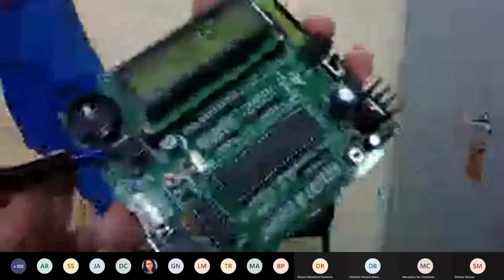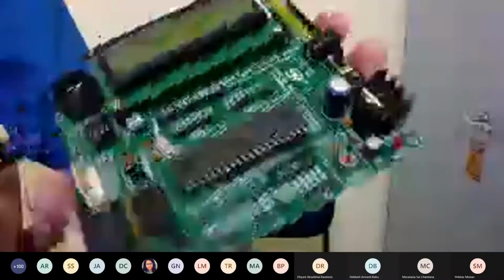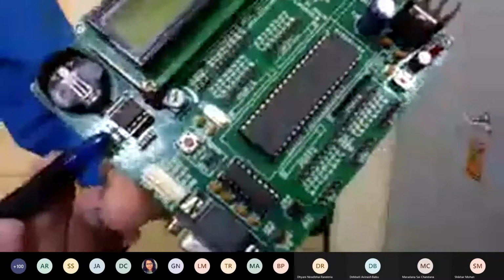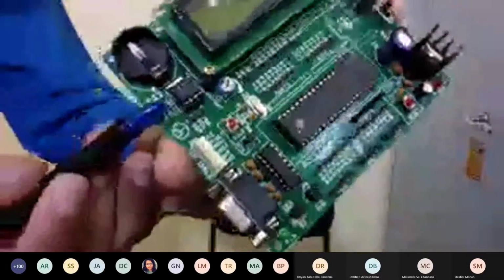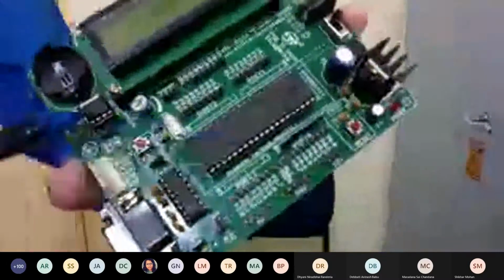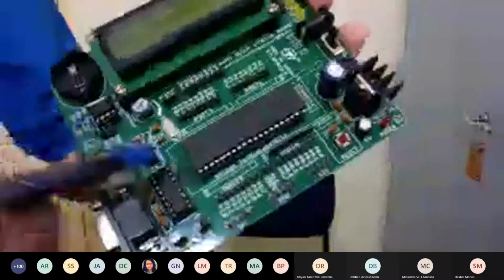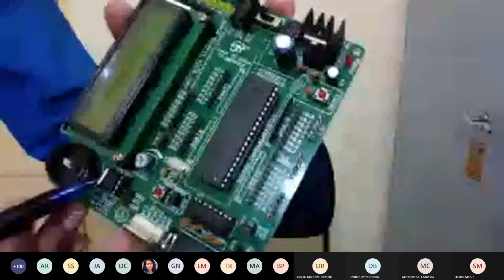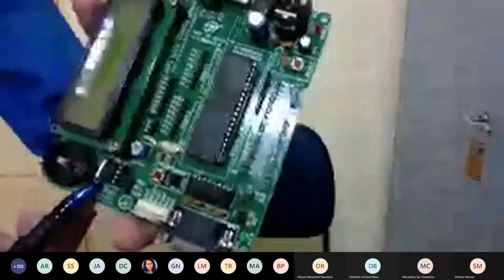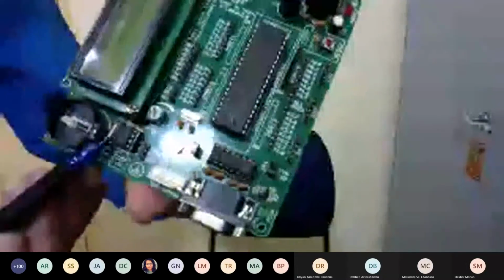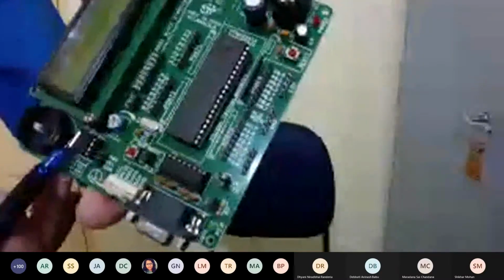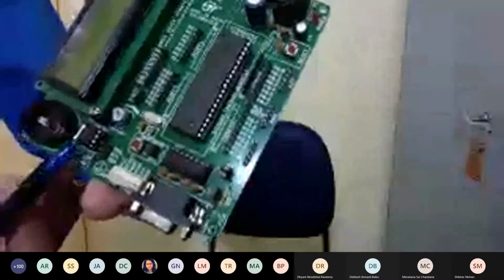But this particular chip is quite small. I think the number is DS1307. This is one of the peripheral chips which is interfaced through one of the serial communication protocols from the microcontroller. So basically it is connected by using some serial input output pin with the microcontroller. But this chip is using a crystal. You can see there is a little crystal over here, this shiny cylindrical thing. This crystal is the time base for this particular clock.